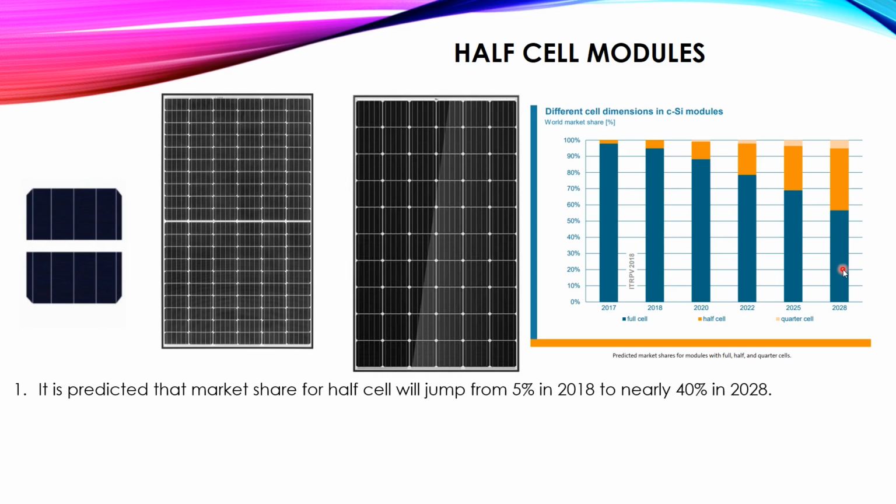So in this lesson we discussed the half cell modules, the shading effect, and the difference between having bypass diodes and not having bypass diodes, and why half cell modules are the future, or why they are important.